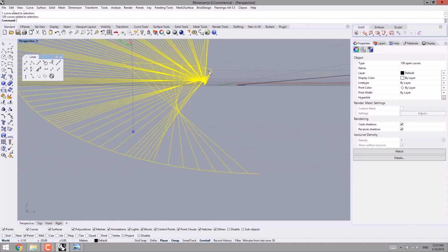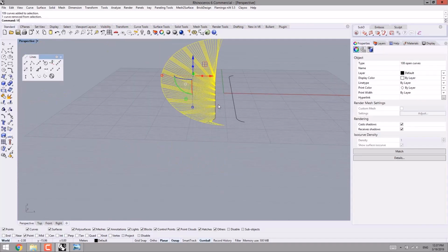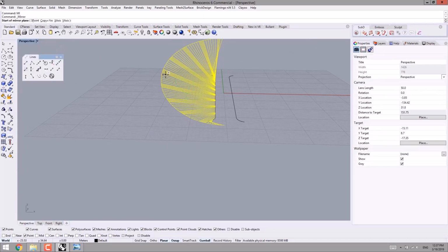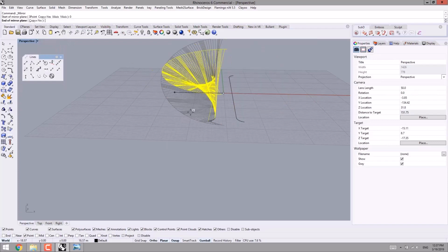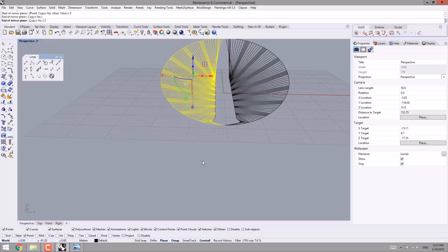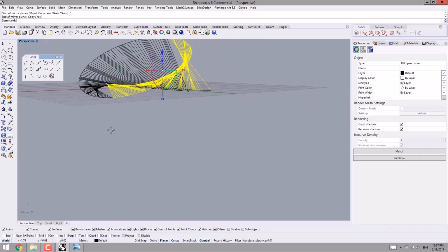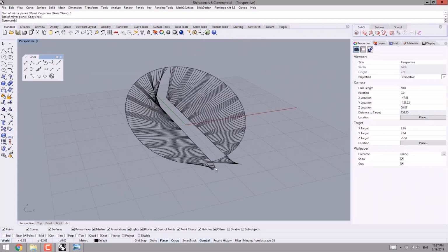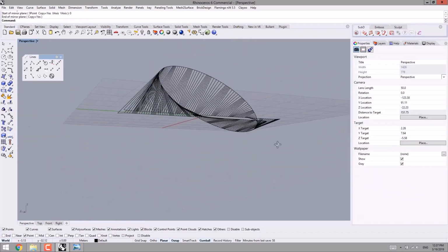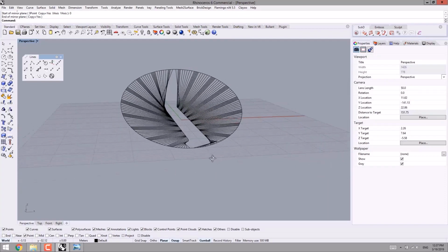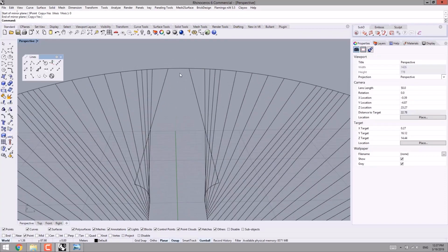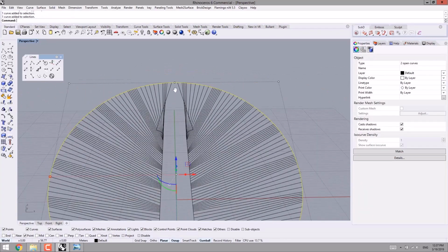Then I select the entire lines or curves, and I deselect the ones I don't need. I type the mirror command in the command line, MI. Then I start the command. I sketch the axis from the midpoint, the origin point. Then I mirror it at the other side, like this. So, as you can see, the elliptical bridge is getting completed.